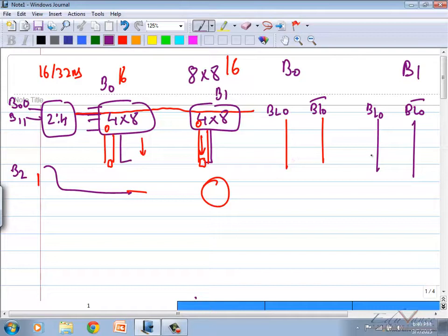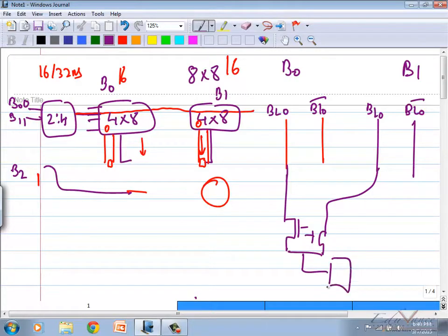Question is, should I put 2 sensamps here or using column enable short it and then give it to sensamp? पॉसिबल है ना? Yes or no? मतलब दोनों बैंक का कंबाइंड एक नीचे सेंसैम्प, मैं डिसाइड कर रहा हूं कहां से डेटा आना चाहिए. करेक्ट? Yes or no?